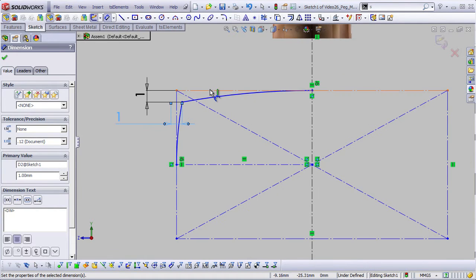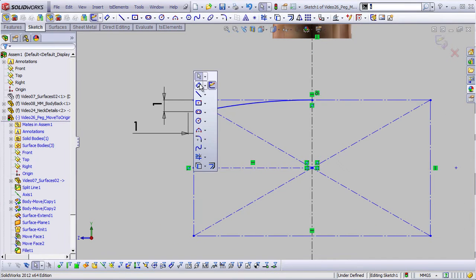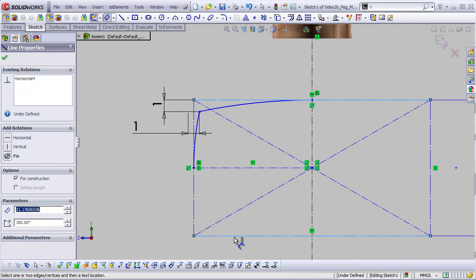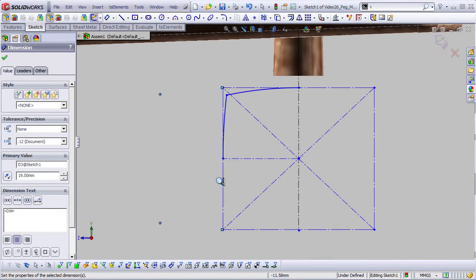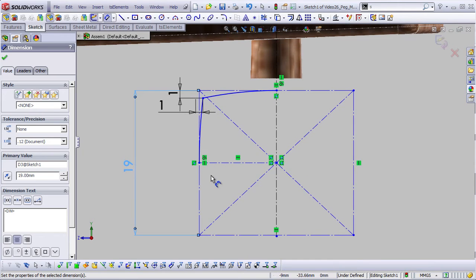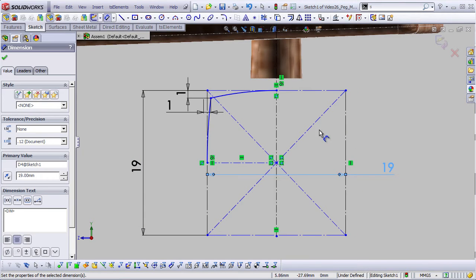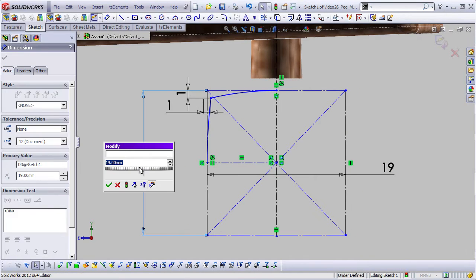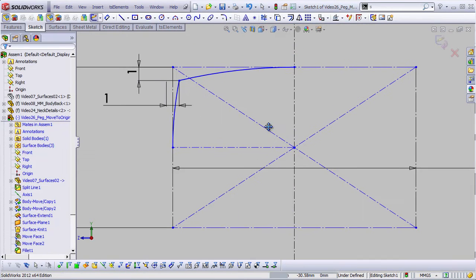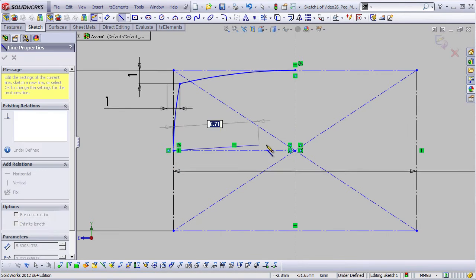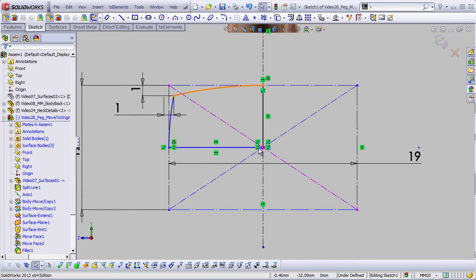And now we just have to define the overall dimensions of our key using this rectangle that we have here. So let's set our overall height to be, I don't know, let's call it 3/4 of an inch, which is about 19. Actually, I think I want this one to be 19. There we go. I want it 3/4 of an inch wide, and I'm thinking this probably wants to be a 1/2 inch, more like 12 millimeters. There we go. That looks better. And finally, I'll just grab my line tool and just close this up so we have a solid here. That'll be useful. All right, so that looks pretty good to me.